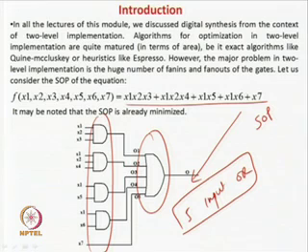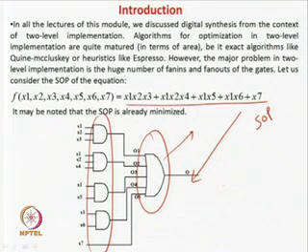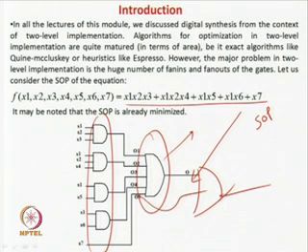Now what is the problem? There is no problem implementing this mathematically. This is a minimized two-level implementation, but the idea is that implementing this OR gate with 5 inputs is a big problem, because the more fan-ins a gate has, the slower it will be in operation and the higher its power consumption. So what we do is try to break it up into 2 OR gates maybe. For a good implementation, you can put another OR gate over here, and the fifth input you can put over here.